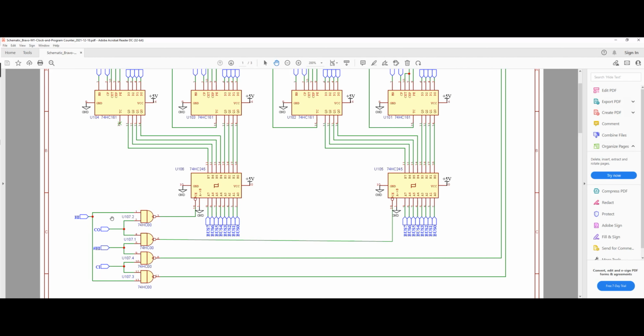Therefore, when it comes to our NAND gate, one input is going to be low, and therefore, even if you have the counter out signal, the high byte is not going to have an output. The output of the NAND gate is only low if both of the inputs are high. So as you can see here, we have deactivated the high byte.